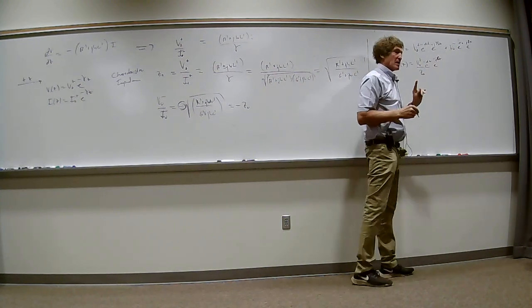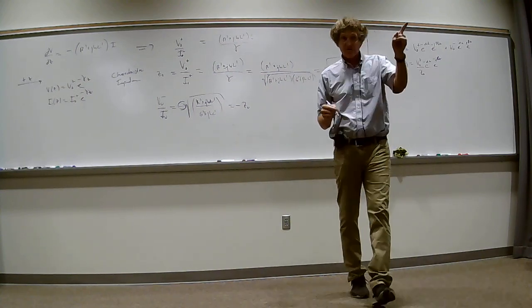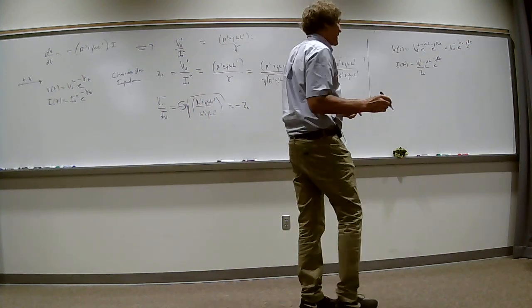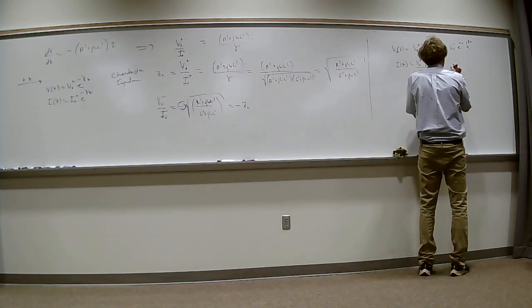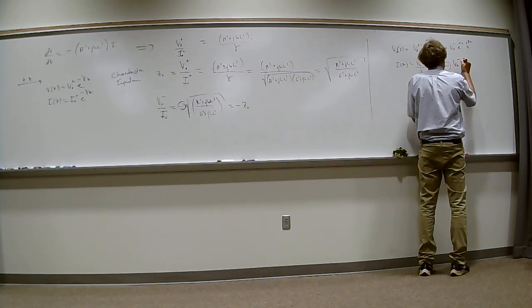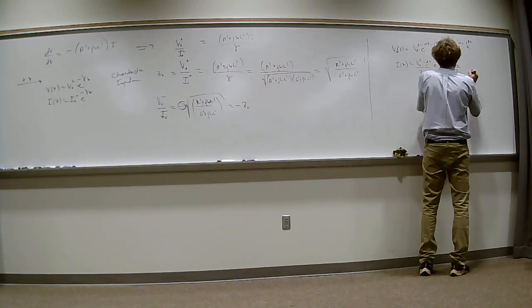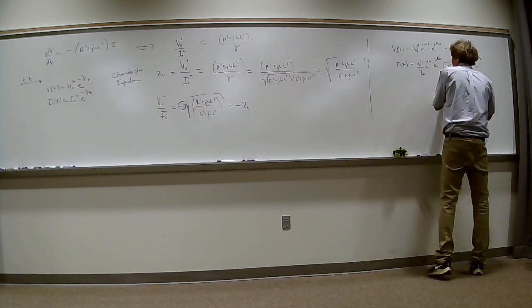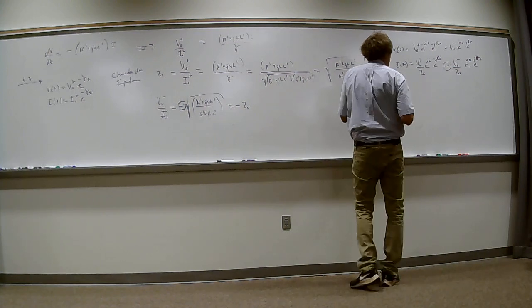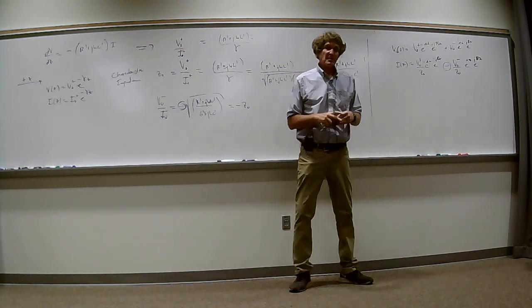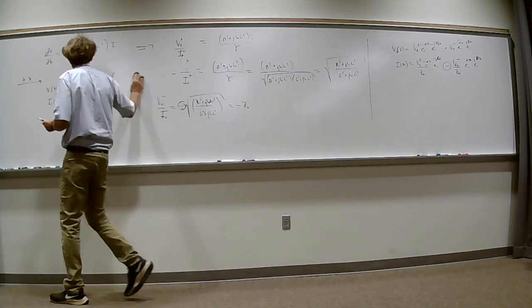This is the important one. Remember I said the ratio of V0 minus to I0 minus was negative Z naught? You all remember that? What that does is make this next term negative. Circle that. It's going to be minus V0 minus over Z naught times e to the gamma z, e to the plus j beta z. Okay, those are the two equations that are going to dictate behavior on the transmission line for V and I in the phasor domain.